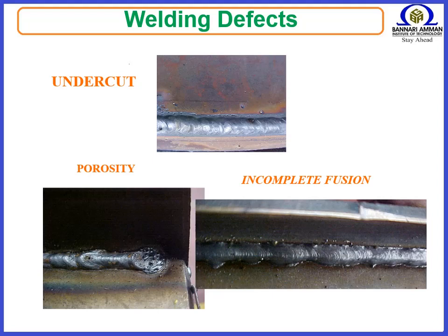Causes of undercut: too high weld current, too fast weld speed, the use of an incorrect angle, which will direct more heat to free edges. Porosity. Porosity occurs as a result of weld metal contamination. The trapped gases create a bubble-filled weld that becomes weak and can with time collapse.